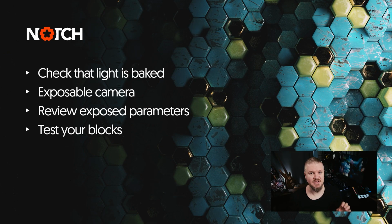So, always check that the lighting is baked where necessary, and don't forget to make sure that your regular camera is replaced with exposable camera. Of course, it is smart to review exposed parameters too. And test your block, preferably in a media server, but if you do not have access to it, use Notch's own media server emulator, FX Player. So in the next workshop, let's export a Notch block and let's use FX Player to play it back.